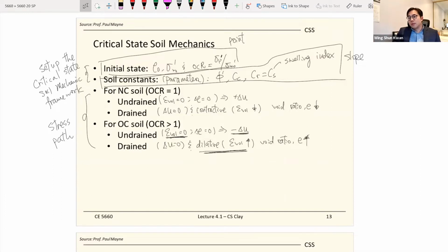data point. And also knowing the stress history helps you, because sometimes you're not on the normally consolidated line, but you may have a rebound going on. You're on the overconsolidated line or consolidated line. So that's why you will also want to know about the OCR, the stress history. One more time, the key concept here is always knowing where to start and knowing where to end. So you kind of start giving you some constraint when you try to do the modeling.